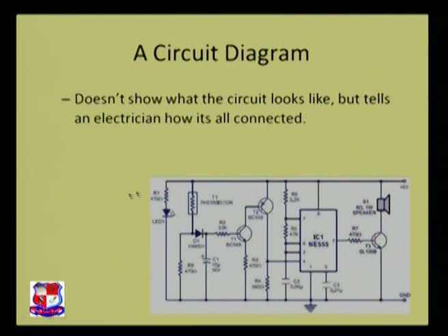You must draw the drawing, and it also indicates the technical details, but it does not look like the actual thing. Over here a resistor symbol has been shown, but the resistor does not look like this. It is the symbol for the same, but it indicates all the technical details: that it is R7 and it is a 470 ohm resistor. Over here a speaker has been symbolized, but it indicates the technical detail that it is an 8 ohm 1 watt speaker.